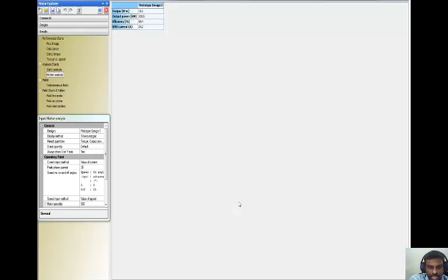In transient analysis we have two things. Click the motion analysis in the result window, and if you drop down the display method, we have four different types available: one is time average, one is waveform, and another is harmonic content in phases. So the first thing is I set the display method as time average, and in result quantities I choose torque, output power, efficiency, and RMS current.